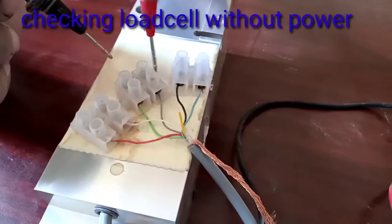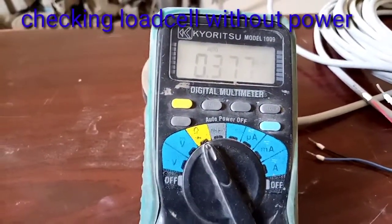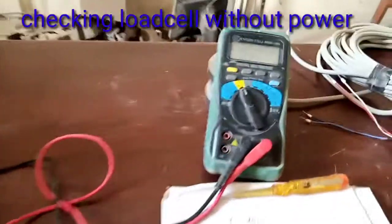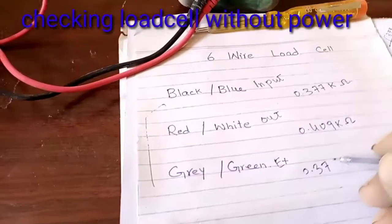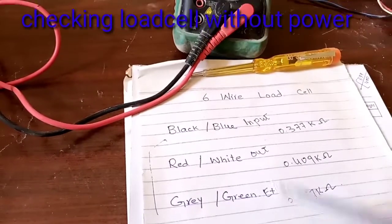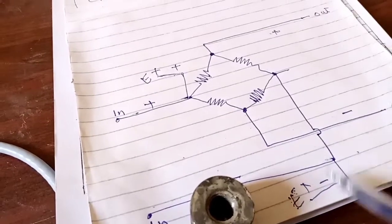We can check here green and gray wires. You can see on the meter 0.377 kilo ohm. So I can write here 0.377 kilo ohm, and you can see on the page, input wires and excitation wires resistance is the same, like these are the same wires.